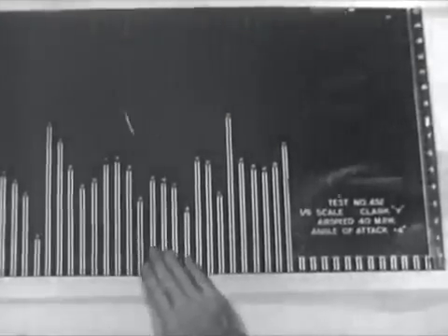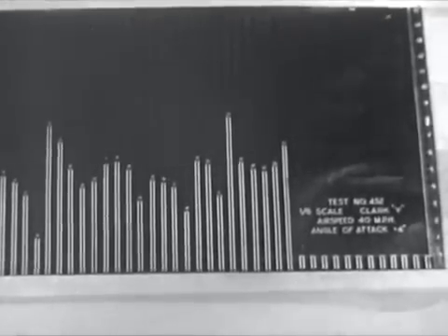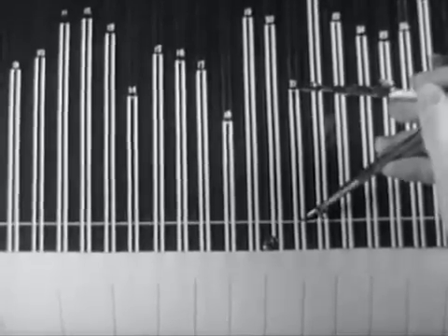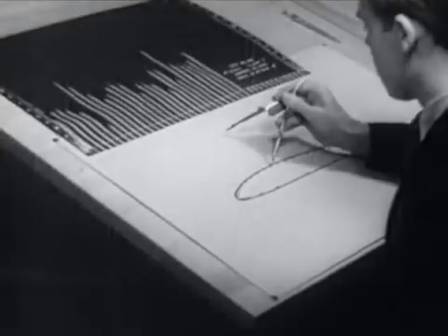Levels fluctuate slightly as minute variations in airspeed or density occur, but the ratios are constant, and the position of the liquid in the tube shows both positive and negative values for the airfoil. The tubes are photographed to assure simultaneous readings of all tubes, and the photograph is used by engineers to plot the pressure curve.